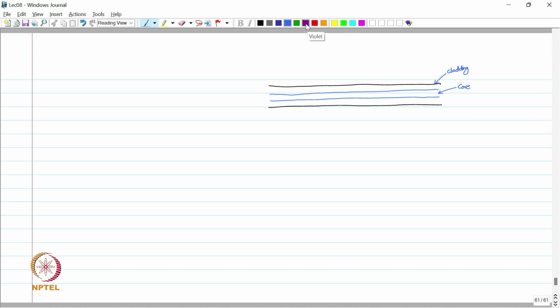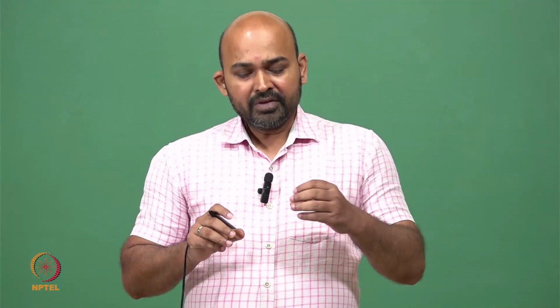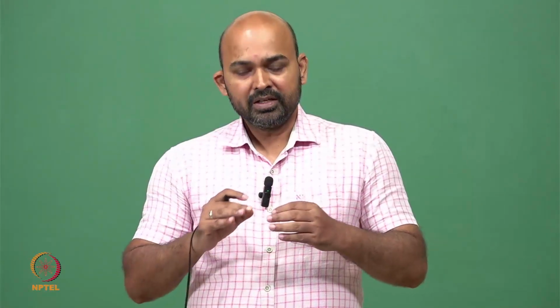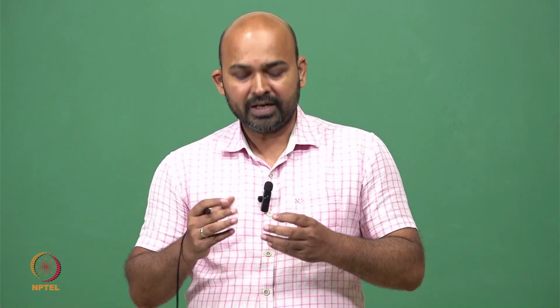If we make certain discontinuities, for example, we put some grating here in the core, so if in this fiber we have introduced certain discontinuities, which are the fringes here, whenever this optical wave sees a discontinuity, it tends to refract at that interface.